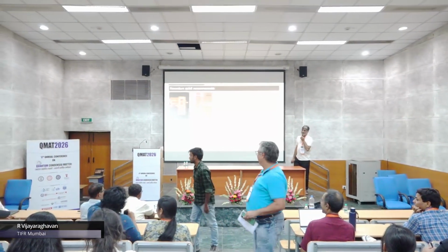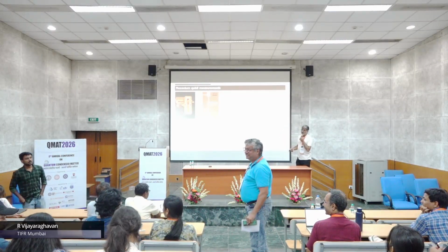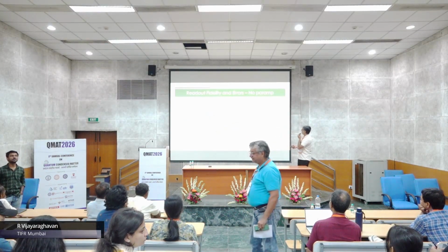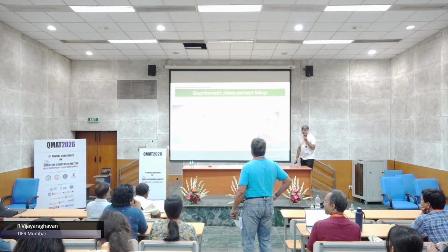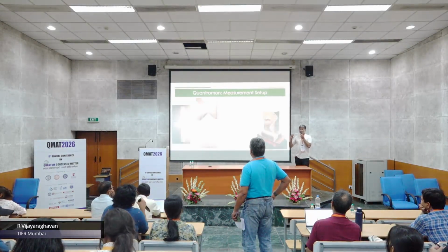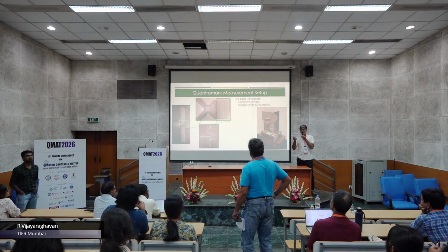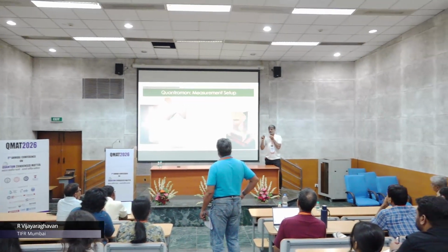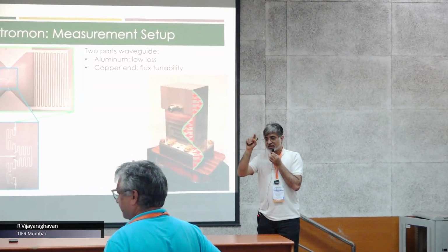Yeah, thank you. So there was this box which you showed where you said that you want to also use a magnetic field in there. Can you give some numbers on that, because I thought magnetic field is detrimental to these things. So in general, magnetic fields are bad for superconductors, but those fields are much higher. That depends, of course, on the superconductor itself. These are very small fields whose job is only to introduce about a flux quantum in the loop.